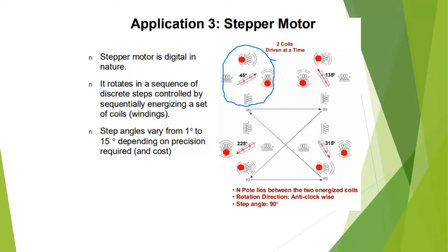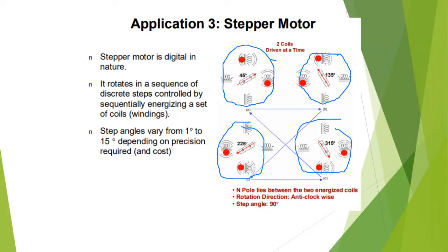So this is like that. So this is, for example, okay. So what we can actually write in a simple format is, for example, A, B, C, D. We have a four-phase system. This stepper motor is a four-phase system, and two phases are on at a time. For example, this one is on and this one is on, but these two are off.